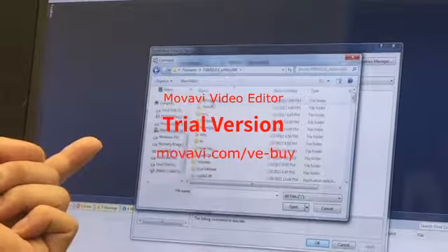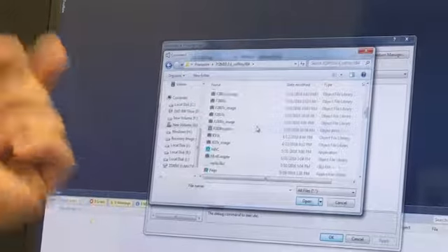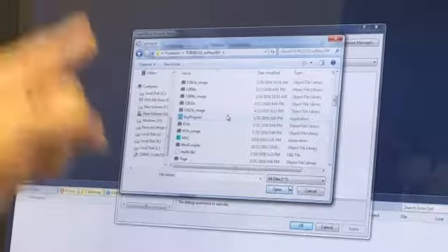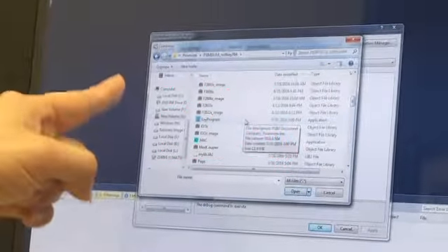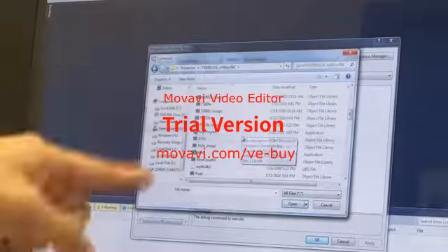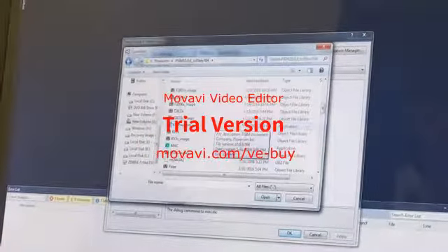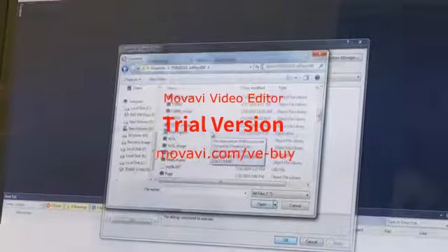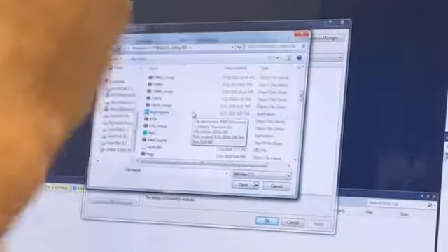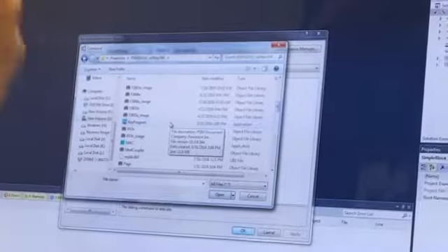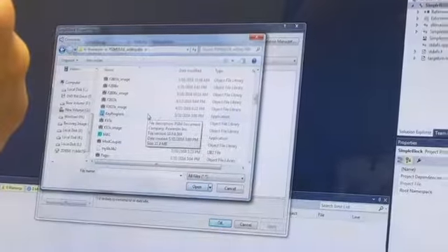We're going to link this DLL to PSIM. So when we say debug, it's going to open up an instance of PSIM, link it to the process, and then when we put breakpoints in our code, we can run the PSIM simulation and it'll break at the appropriate points in the code so that we can debug it.